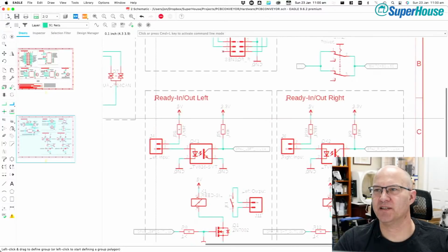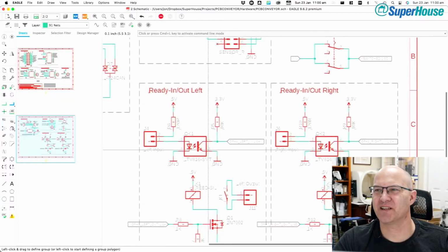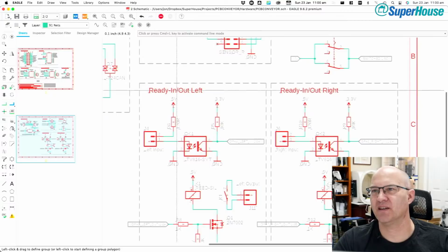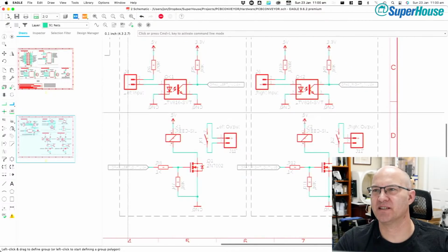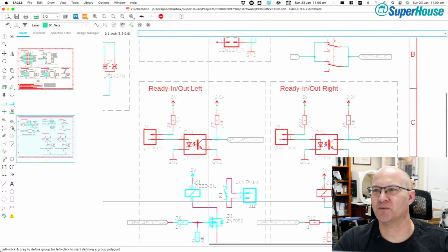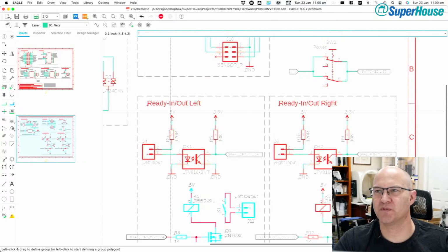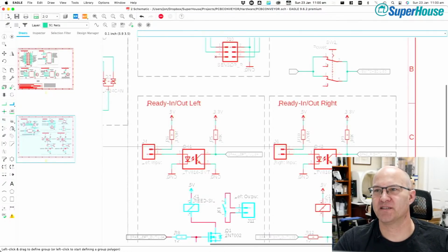On the input side, 5 volt, yeah, okay, that'll do. I was just thinking about design choices here. Okay, so I've got an opto coupler here, and this is the opposite side. If you imagine that the machine at the other side has some kind of dry contact output, and we want to read from it, we provide 5 volts through a current limiting resistor, and it goes out this connector and then through their relay, and then comes back in again and drives this opto coupler.